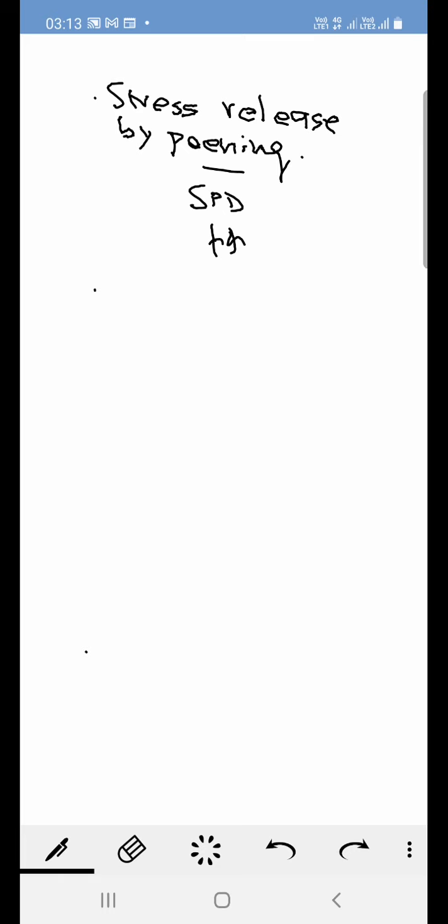Secondly, you remove some tool marks. Suppose the metal, for instance, has been used for some previous applications, and there are some tool marks. By abrasive blasting, we can remove any tool marks on the material.